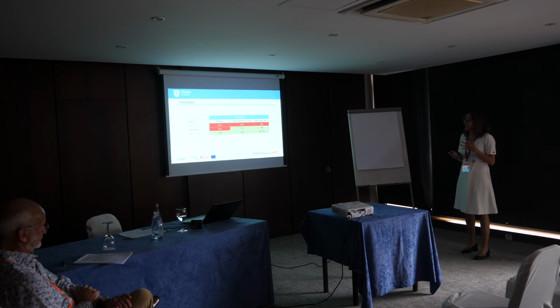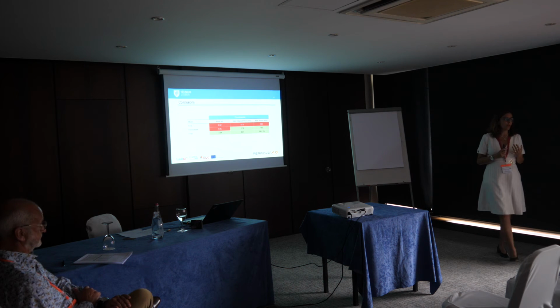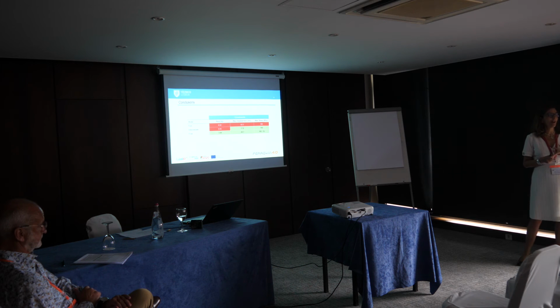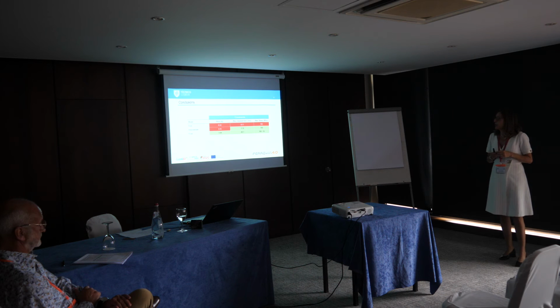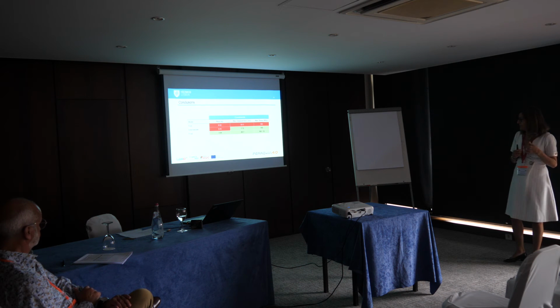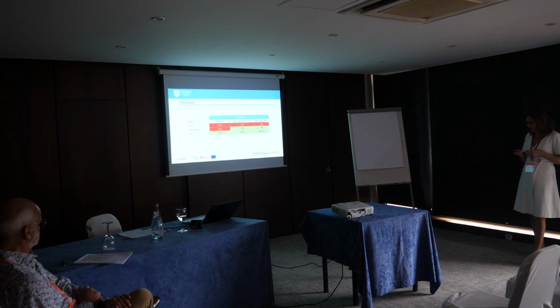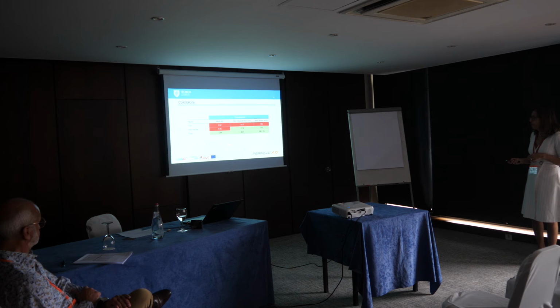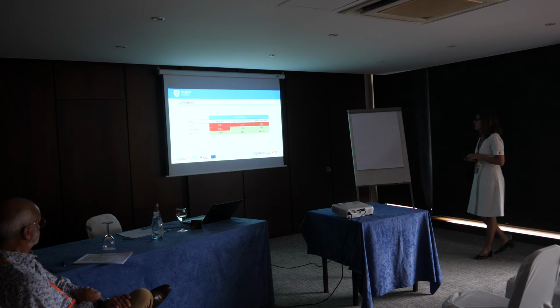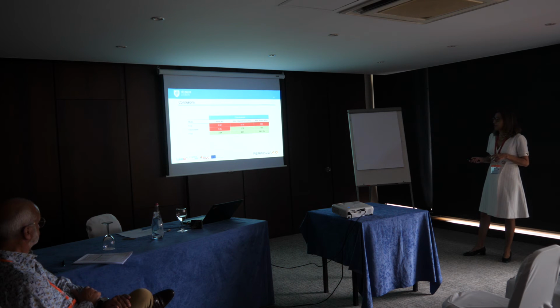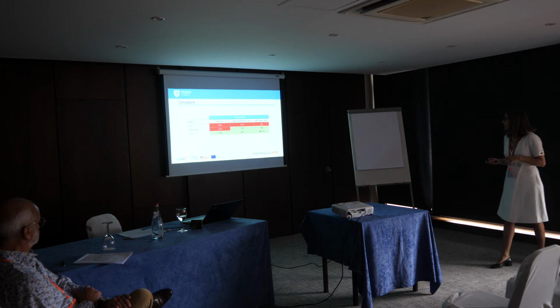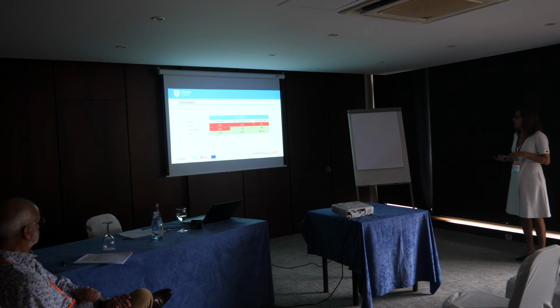Concluding, here we can see the values of the first, the second, and the final model that we studied. In red, we have the values that are higher than the constraint defined, and if you look, the final one is the only model that respects all the constraints in terms of the total mass defined, the maximum displacement of the headrest, and the maximum von Mises stresses.